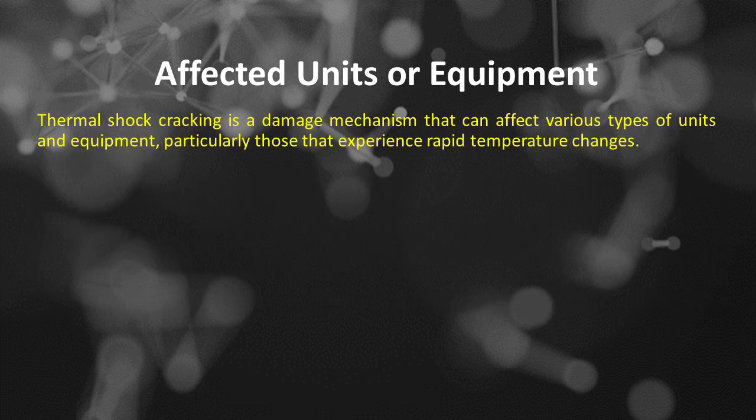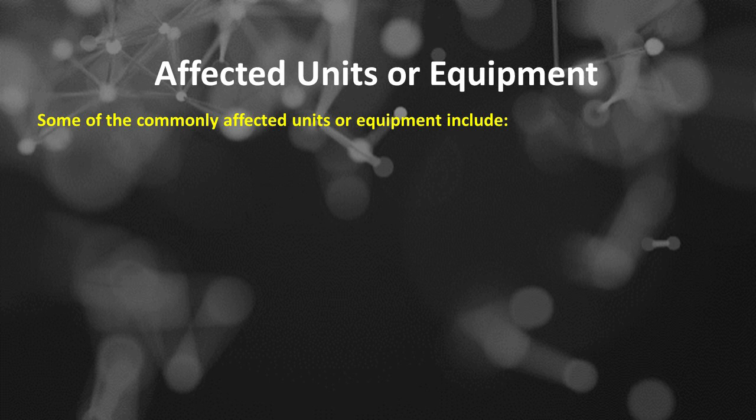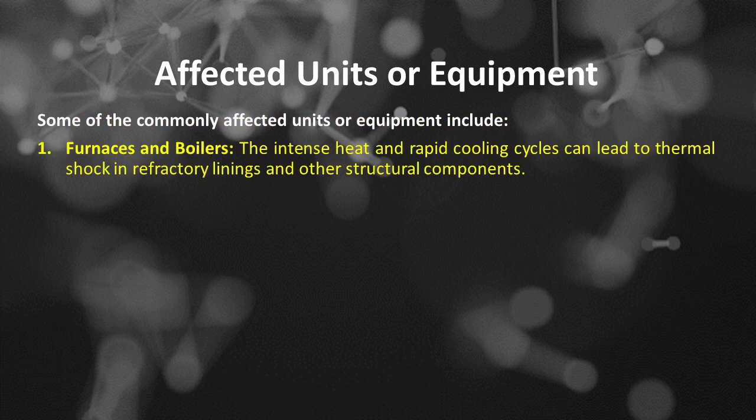Thermal shock cracking is a damage mechanism that can affect various types of units and equipment, particularly those that experience rapid temperature changes. Some of the commonly affected units or equipment include: Number 1 is furnaces and boilers. The intense heat and rapid cooling cycles can lead to thermal shock in refractory linings and other structural components.